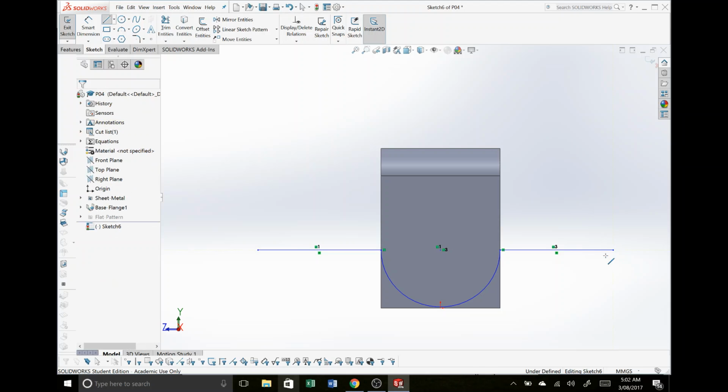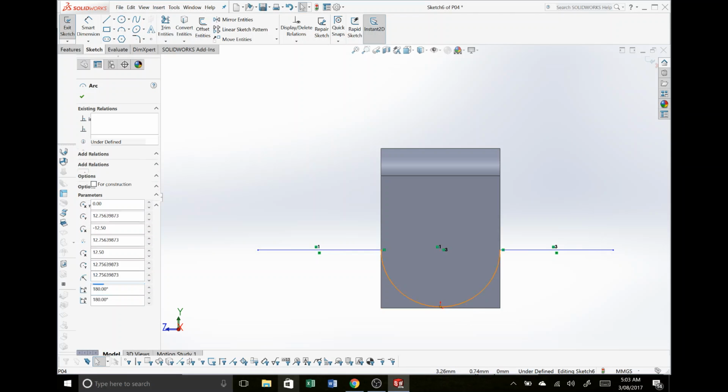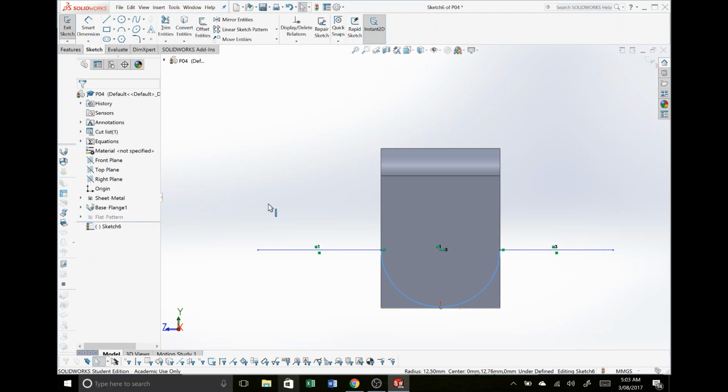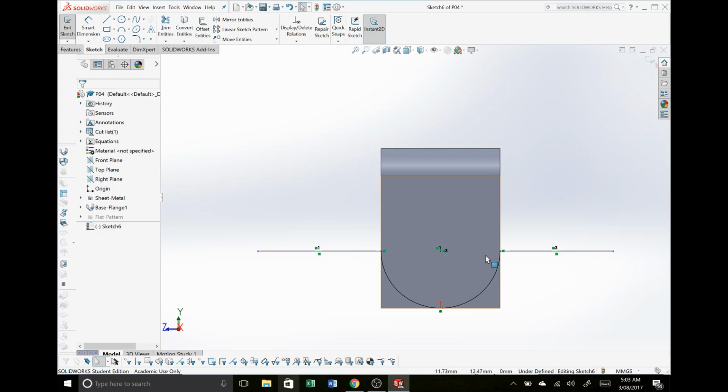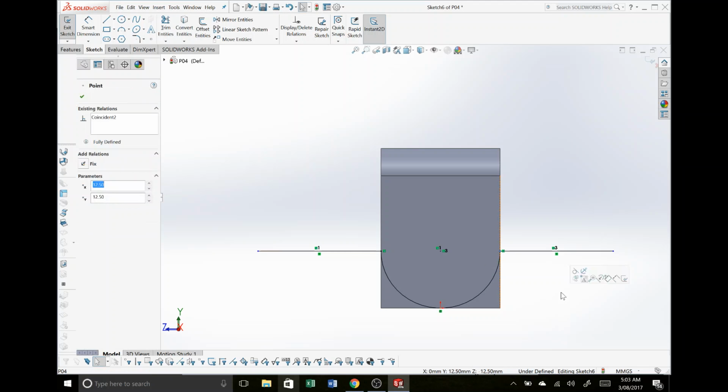And what this is going to be used for is to cut away any material below that sketch so that we can remove the bottom of this arc and make it look like a nice, lovely, rounded bottom U-bracket. Now, I can see that bottom's not touching. I'm going to put a tangent dimension on there. We went over that in a lot more detail in class about what that does to the geometry and why we want that. And now that's looking pretty nice and good. It looks like we got a good bit of tangency going on there.